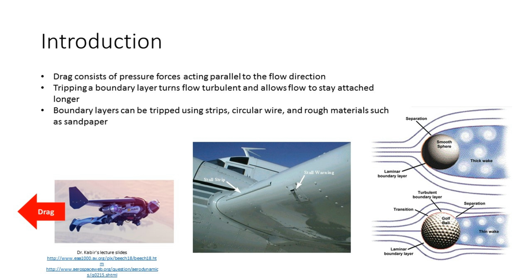A cylinder has a more aerodynamic shape than a cube or rectangle, so the shape won't be the main cause of turbulence, but it has an easier shape to trip the boundary layer on than an airfoil. A cylinder should clearly show where the flow separates and how Reynolds numbers will affect the flow regimes. The lab also observes the effect of tripping the boundary layer, which is achieved by placing some kind of obstruction at the location of flow separation.